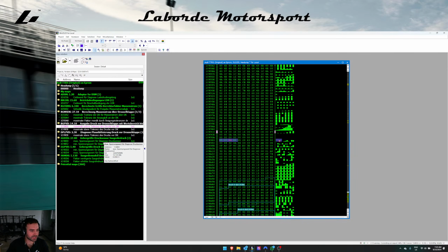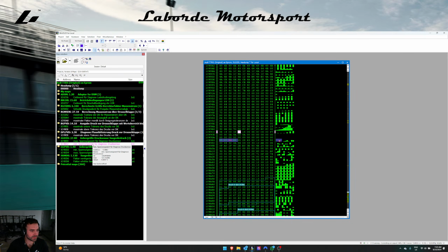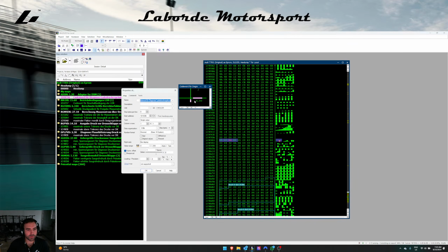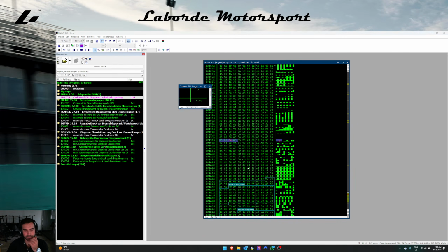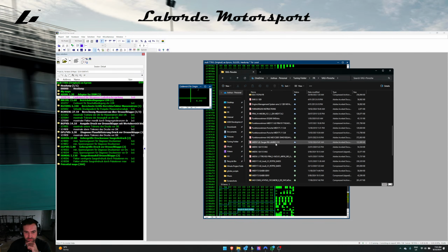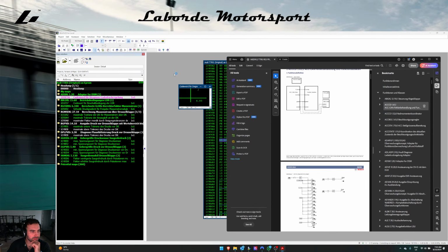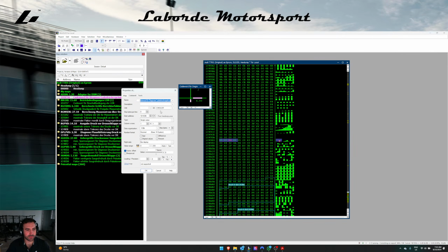Like I said, I've already explained why I'm doing this. It's not to turn off any safety systems. It's more for the fact that we need to get above that 255 kPa internal 8-bit variable limit. Now with these here, if you're not sure what these things mean, you can go through some documentation. If I go to VAG and then something like this, let's say we want to go to the ADSM module. So we go down ADSM, and I'm going to copy this code word.